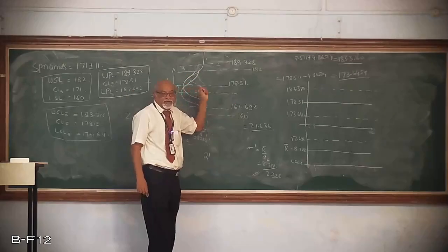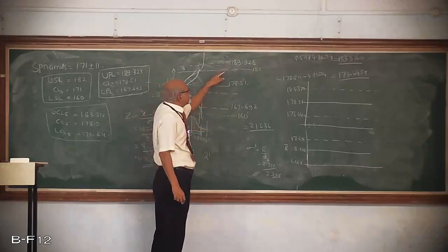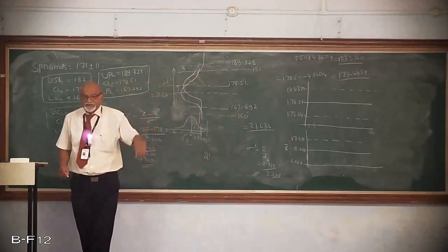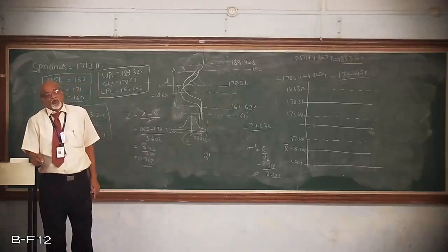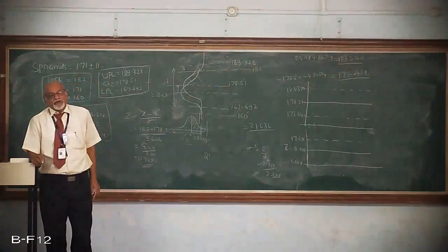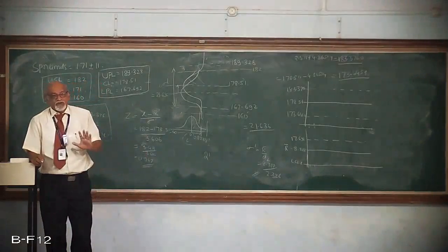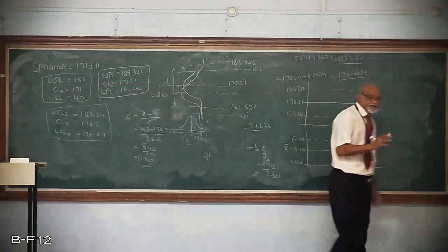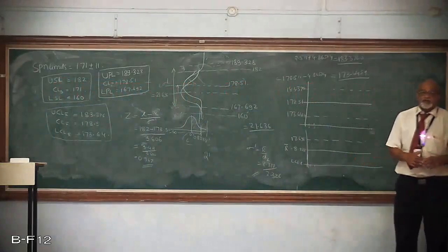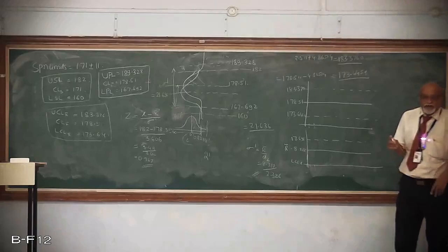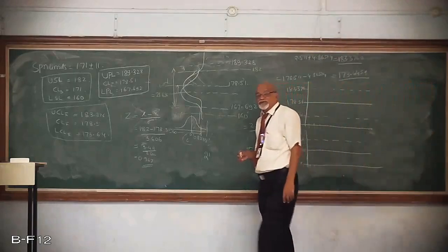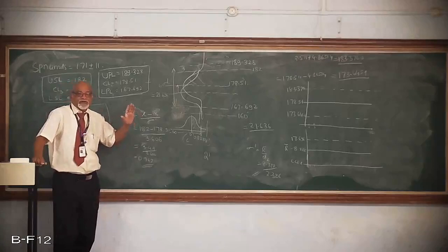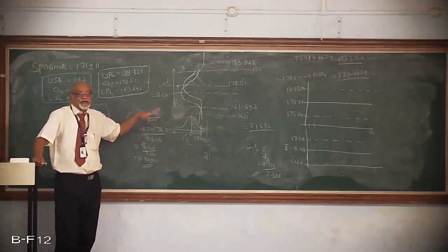I will adjust in such a way that the upper specification limit and the upper process limit are the same. In that case, what I can observe is only 0.0135% of rework. Not more than that. Try to understand. From 18%, we can reduce it to 1% hardly. That is what you can think. So the colossal waste has been reduced.